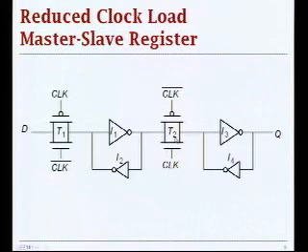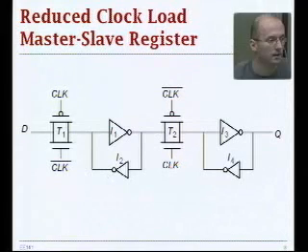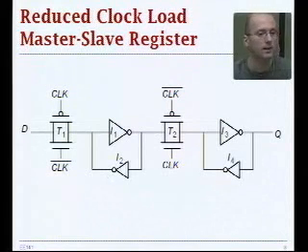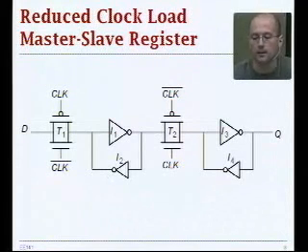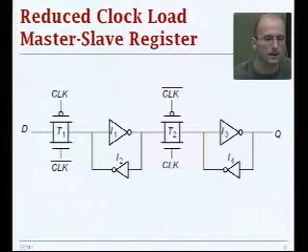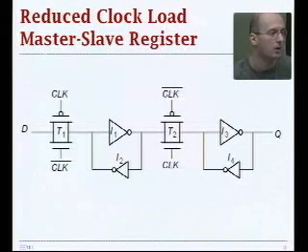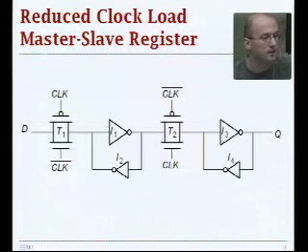So here is an implementation that is based on overpowering. Basically, the idea here is that if I'm introducing another transmission gate here to break the feedback loop, then the problem is really when I have thousands of these in my real system, and then I have to clock all of them, then I'm effectively sort of doubling the clock frequency. Not necessarily doubling because there are sizing issues, but I'm increasing clock load significantly, and that translates into power consumption.